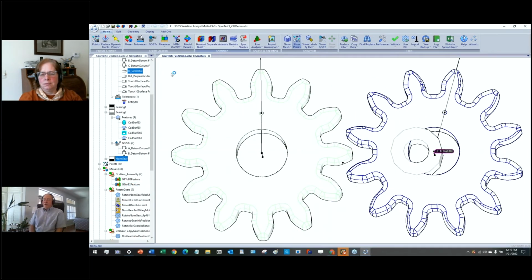The next thing we're going to look at is the flank test. Flank test is a visual check to see how the gears are contacting. And this allows us to make sure they're contacting in the center and not at the tips in the wrong part of the rotation. This is done by running the gear module and then using deviation with a sweep.